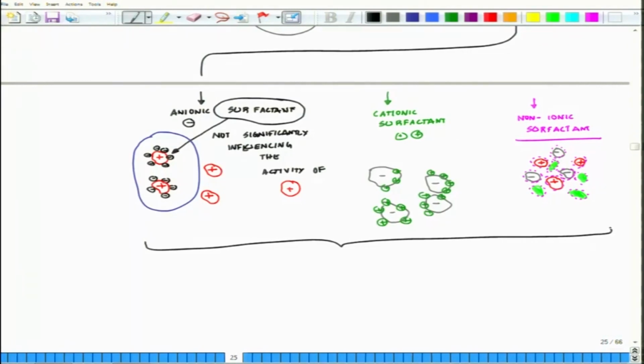Okay. So, this is what is called the ball milling technique, high energy ball milling, where surfactant molecules are absorbed on the surface of the generated particle and help in lowering their surface energy by creating an organic layer on them, thus preventing them from aggregation. So, the roles of surfactants are this: prevent aggregation, this is important, and reduce the surface energy, as I have already mentioned.